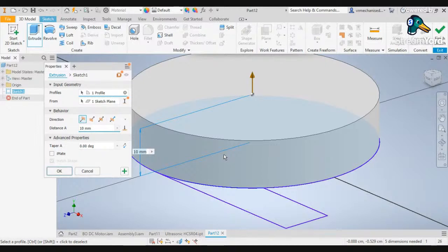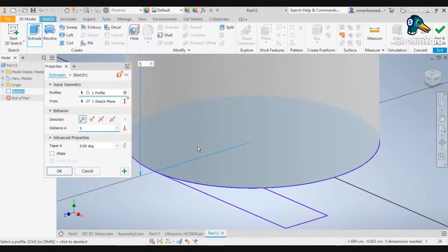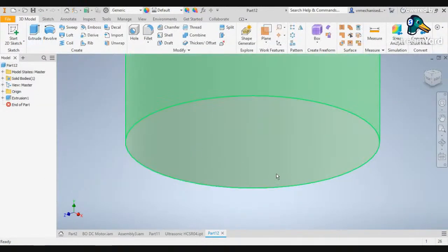And that impeller can be of around a width of 2 centimeters. So usually it is a 5 centimeter part in height. So we'll be extruding it to 5 centimeters. And if we give an allowance, it is around 4 to 5 mm allowance we need to give. So it is considered as 5.5 centimeters. Extrusion has happened.